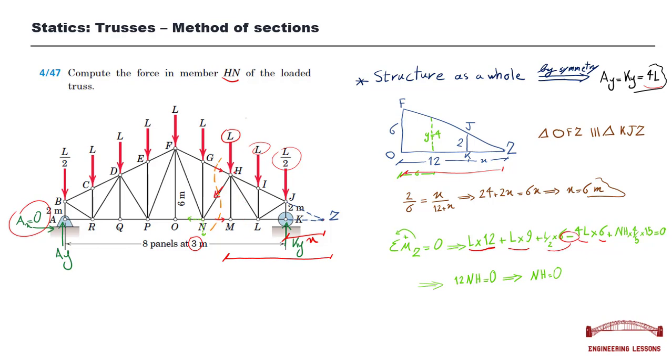Similarly, we could have decomposed our force at point H, but if we decompose it there, our two components cause moment about point Z, and our calculation would be a bit longer, but both of them are right.